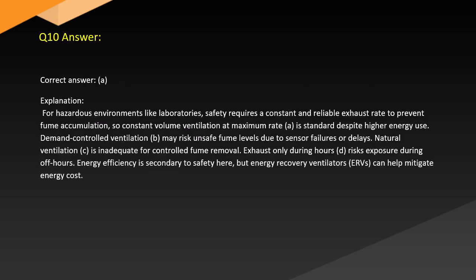Answer. Correct answer: A. Explanation. For hazardous environments like laboratories, safety requires a constant and reliable exhaust rate to prevent fume accumulation, so constant volume ventilation at maximum rate, A, is standard despite higher energy use.